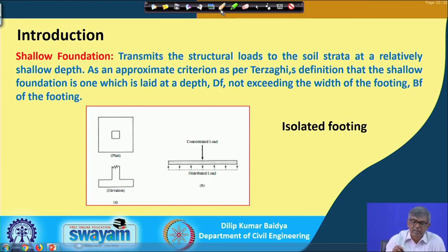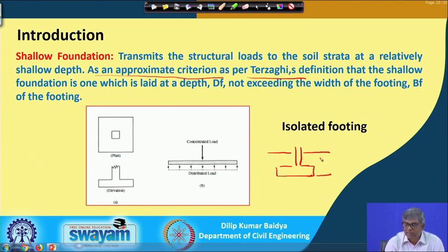And Terzaghi gave a guideline, an approximate criterion: as per Terzaghi's definition, a shallow foundation is one which is laid at a depth Df. If this is the foundation and this is the ground surface, then this is called the depth of foundation Df.